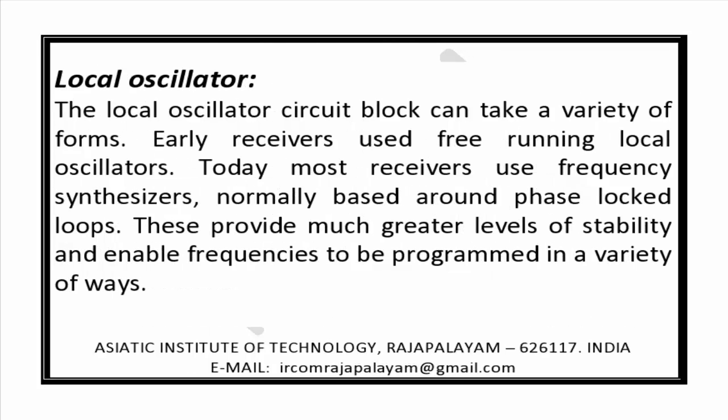Local oscillator. The local oscillator circuit block can take a variety of forms. Early receivers used free-running local oscillators. Today, most receivers use frequency synthesizers, normally based around phase-locked loops. These provide much greater levels of stability and enable frequencies to be programmed in a variety of ways.